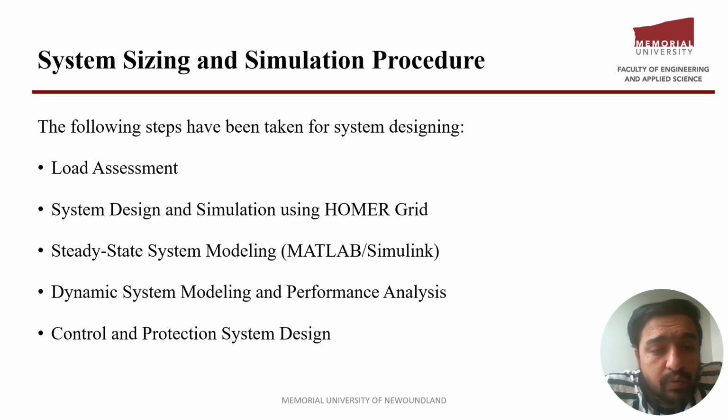Our next slide is about system sizing and simulation procedure. The design process included several steps. We started with the load assessment to understand demand. Then we designed the system and performed simulation using HOMER Grid. This was followed by steady state and dynamic modeling using MATLAB Simulink. We also addressed the control and protection system design to ensure operational safety and stability.